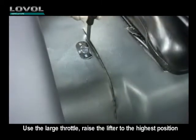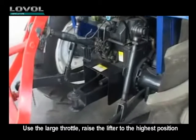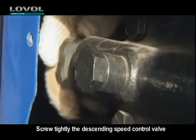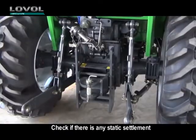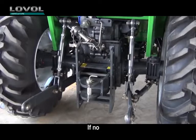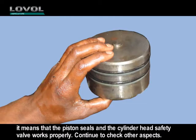Use the large throttle, raise the lifter to the highest position. Screw tightly the descending speed control valve. Check if there is any static settlement. If no, it means that the piston seals and the cylinder head safety valve work properly. Continue to check other aspects.